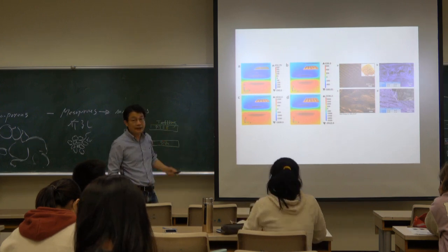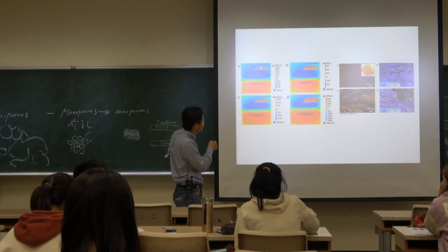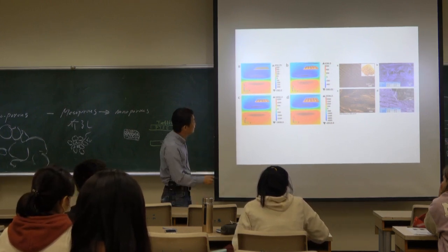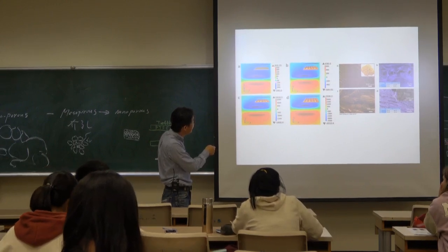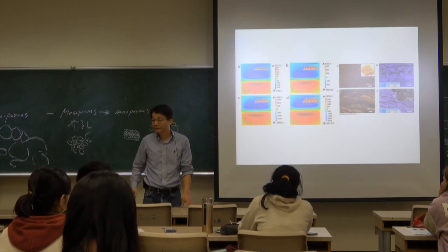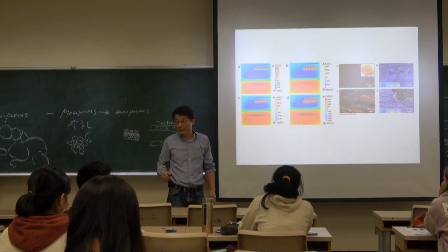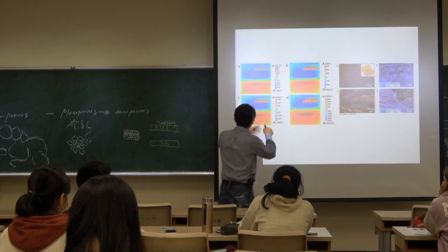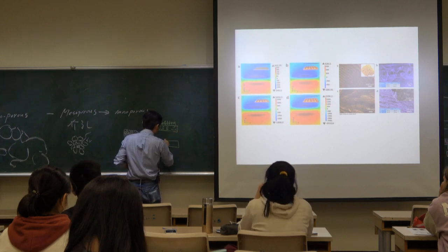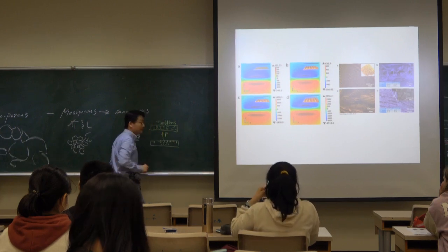This is using COMSOL simulation, finite element analysis. As you can see, once the two plates touch together, suddenly they generate a triboelectric potential. The triboelectric potential is about positive 250 and negative 250. So you can see here polarization, right?